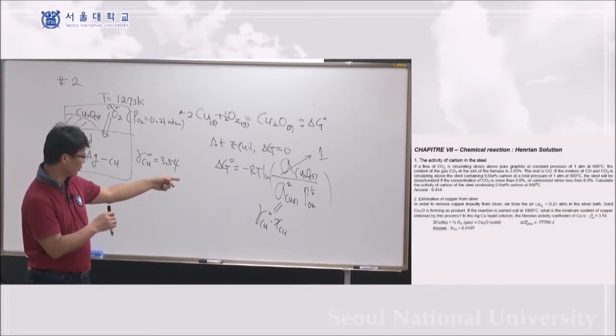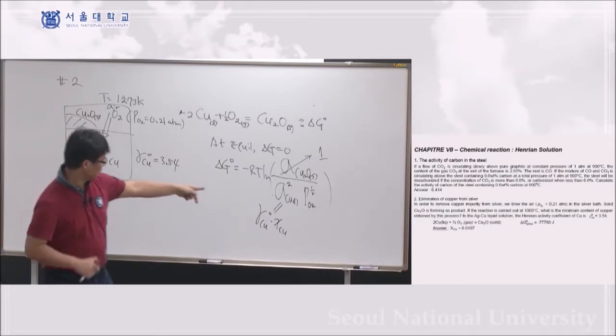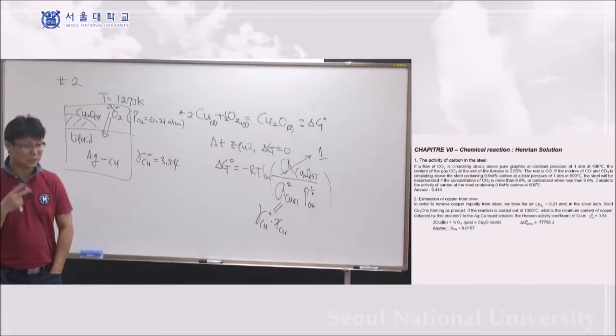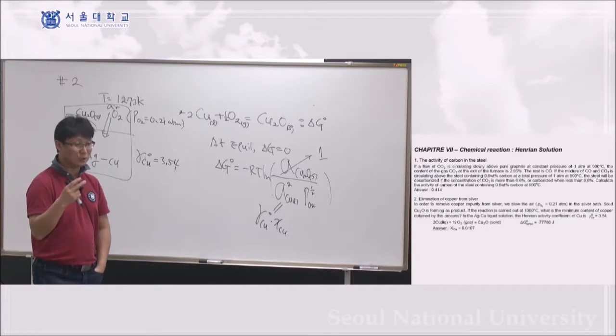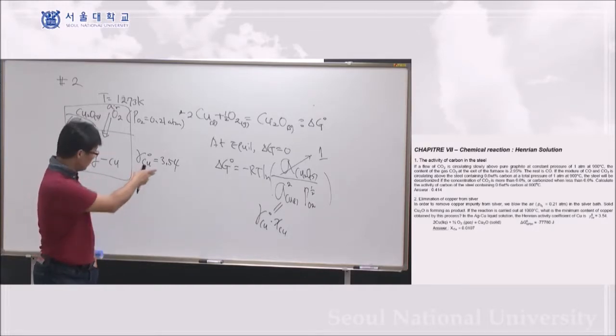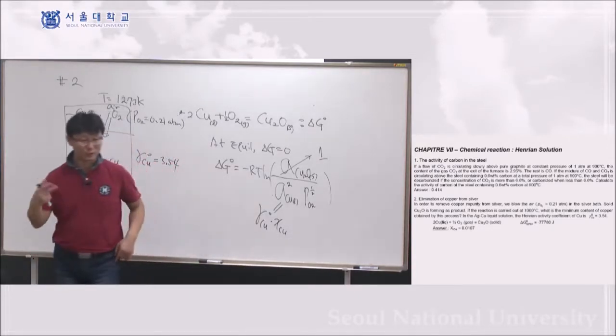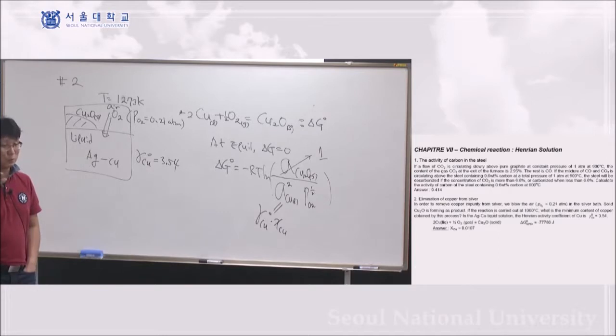So, it's in root, so if you make twice your partial pressure of oxygen, you get about 20% increase of your kappa, but this is square, so probably you can have more impurity reduced than the 20%. That's the first one. And the other one?